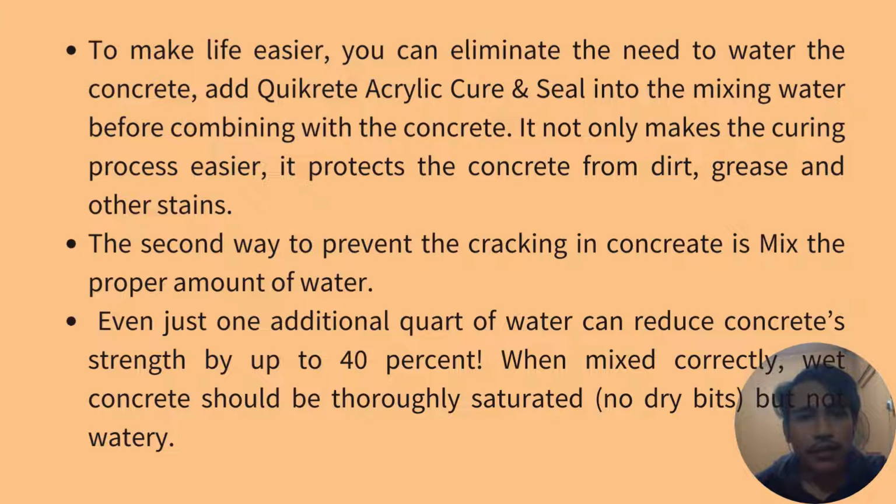The second way to prevent cracking in concrete is mixing the proper amount of water. Even just one additional quart of water can reduce concrete strength by up to 40%. When mixed correctly, wet concrete should be thoroughly saturated but not watery.